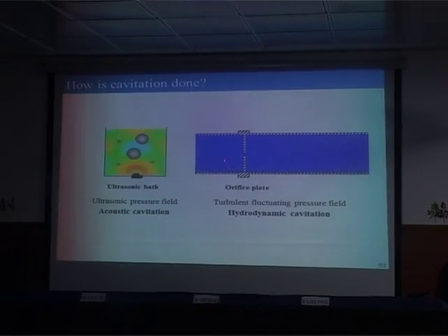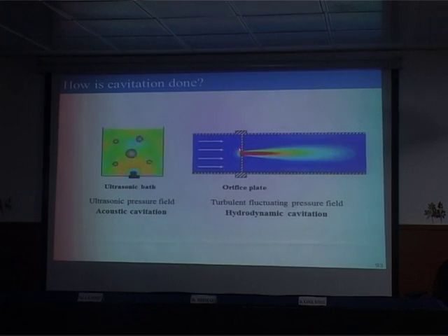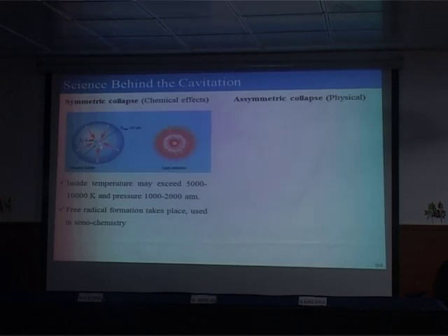And this is hydrodynamic cavitation. Using Bernoulli's equation, you can tell if there is a reduction in the cross-sectional flow area, the velocity increases. Increase in the velocity will result in a decrease in the local pressure. The cavities are going to get generated, and as the pressure recovers further downstream, these cavities are going to collapse. Collapse of the cavities will generate these types of conditions.